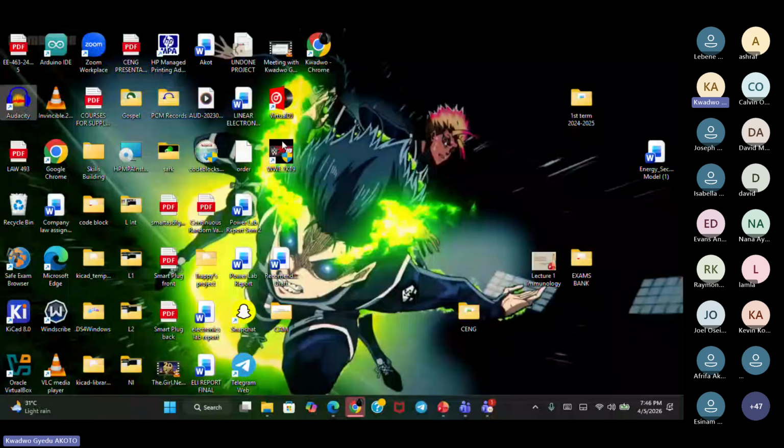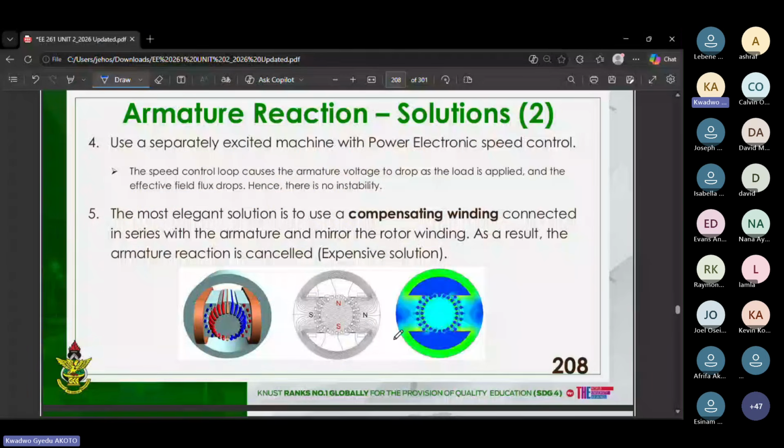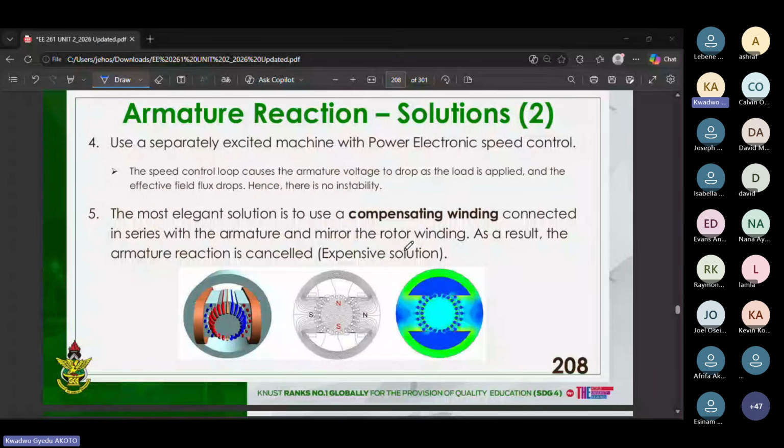And then I'm thinking question 3 is probably going to focus on why you need to add a starting resistance to mitigate a high starting current, right? Or you could also focus on torque characteristics of DC motors, or torque-speed characteristics of DC motors, right? So please keep in mind the application of DC series motors and DC shunt motors as well, right? And why a DC series motor is used for high starting torque applications. And then for question 4, I think he said it in class.